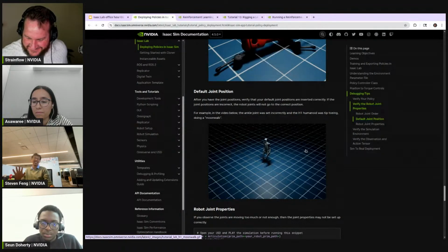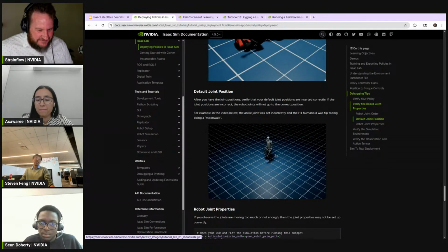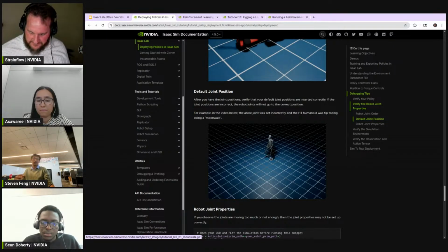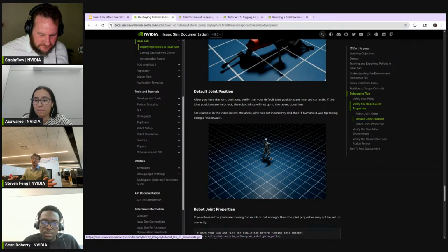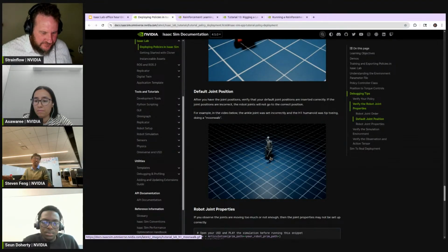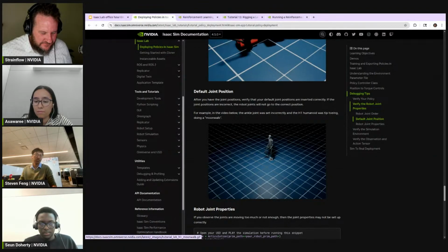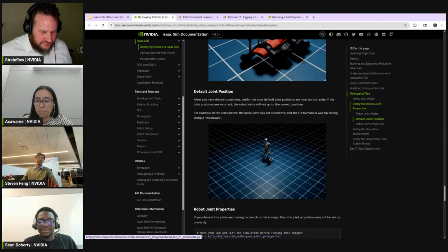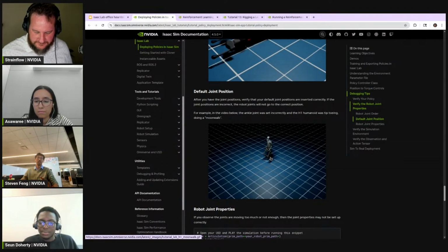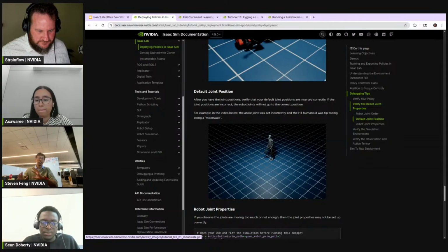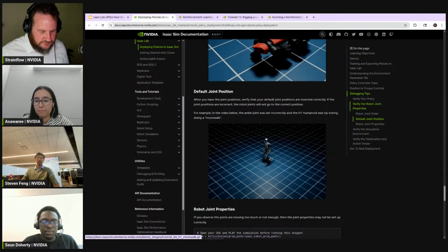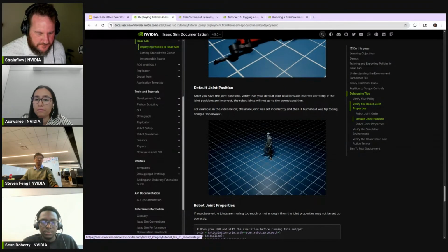It's doing a moonwalk, and it's doing a moonwalk because the ankle joints are supposed to be set, I forgot if it's positive 50 or negative 50, but I did the opposite of what it's supposed to do. So the robot has such a hard time trying to stand up because its default positions are just wrong, and everything it's trying to do, we're adding an additional like 30 degrees to the output.